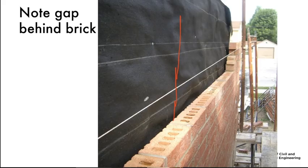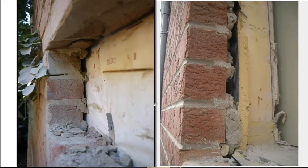So water beads up on this surface, gravity drags it down. So this has been used for over 100 years, since the 1880s, and it's pretty successful. But it does have its limits, in that if it stays too wet for too long, it will rot. And also, not all masonry provides clear gaps.